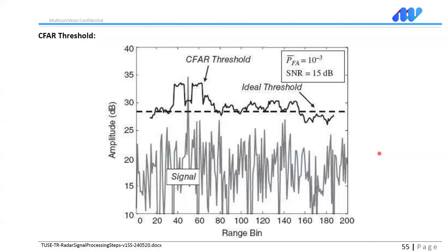So as I said, target detection is done by using a defined threshold. And in radar signals, background noise level often is not constant. So for example, in our MAGIC program, we use range scaling to set this background to a constant number so that we can use detection as a classical method.